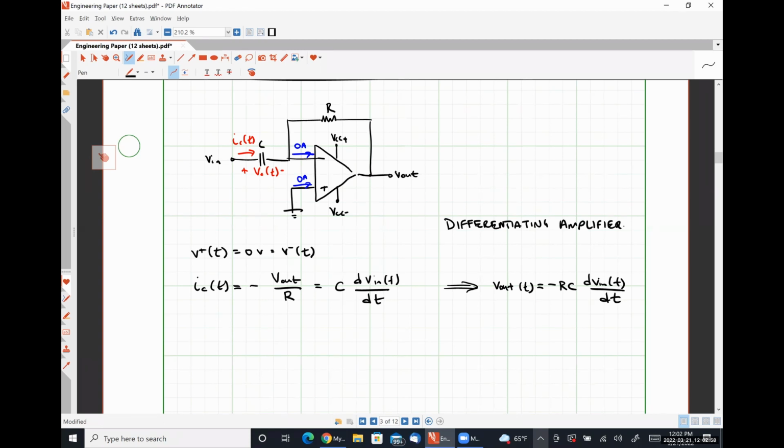So you can make like a coil and then run things out like that, but the more turns you want in your coil to make your inductance larger means the more physical space you have to occupy on your chip. So as I said, generally speaking, the practical realization of these circuits is always going to be with capacitors and resistors. On one of your homework problems, I'm going to make you derive things for an inductor, just because I'm mean, I guess.